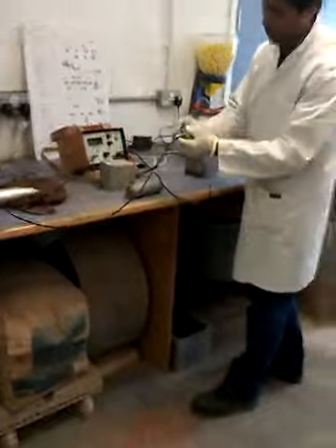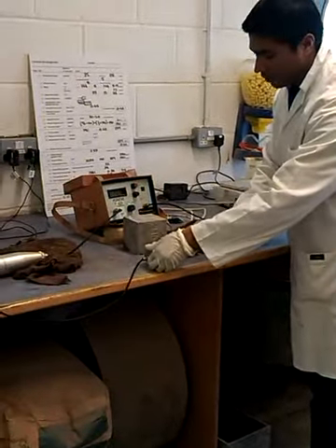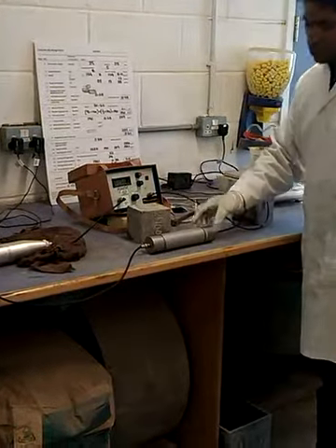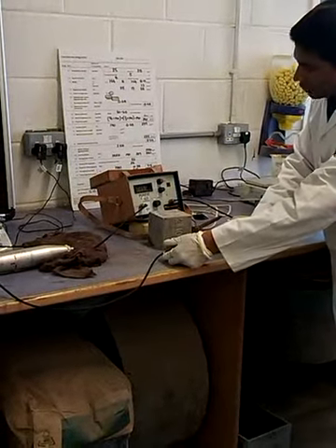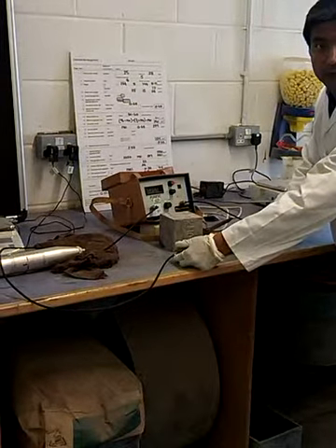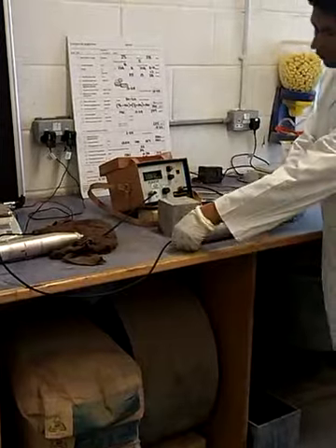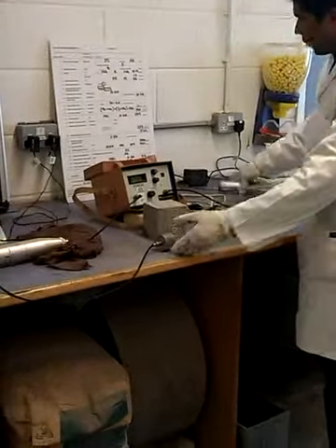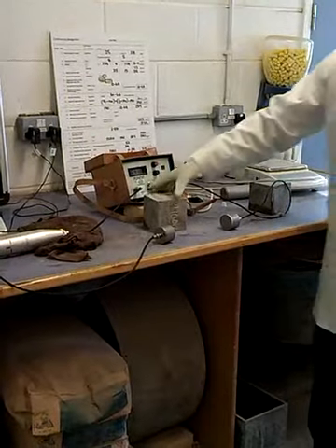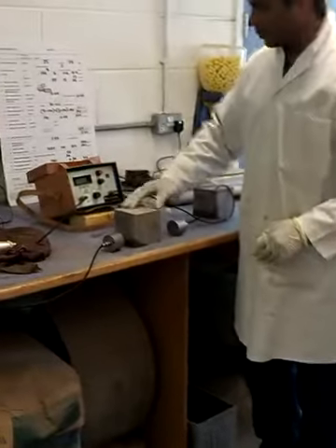The only thing is that when you use the silicone for better contact, keep the transducers opposite to each other. Okay, once you keep them opposite to each other, you see you got the reading of 25.5 microseconds. Once you have that 25.5 microseconds, then that is calibrated. Once it is calibrated, now it's ready for you to use for your samples. Next is how it can be done.